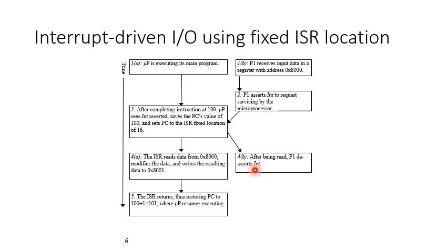The signal is going down, or we can say the interrupt signal is turned off. In the final stage, the fifth cycle, the ISR returns to the normal routine, and the CPU executes the next instruction, loading its program counter with 100 plus 1 because it left the program counter at 100.